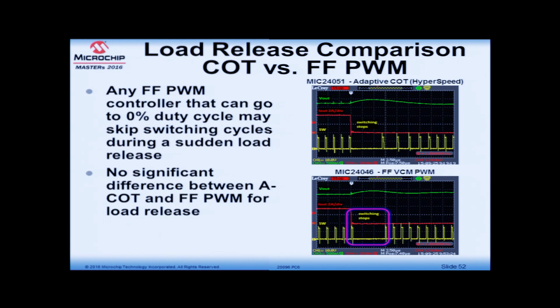At the end, what we will see is that the part will stop switching for a few cycles, and then it recovers its steady state frequency at the new load current value. But what would any fixed frequency PWM controller with 0% duty cycle capability do if you push its bandwidth to the limit and you have a very sudden load release? Well, it will go to 0% duty cycle. So it will also stop switching.